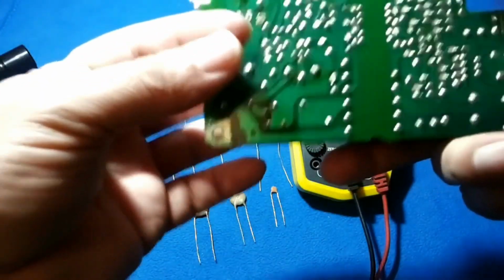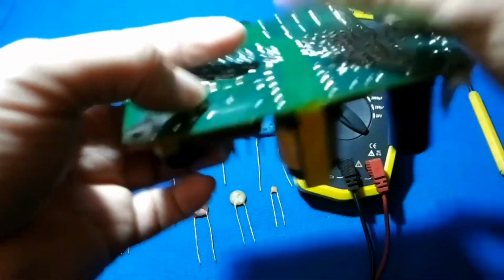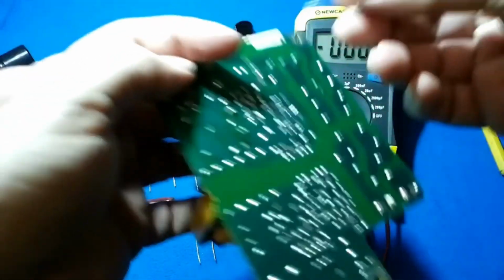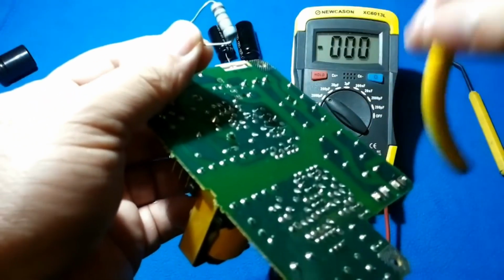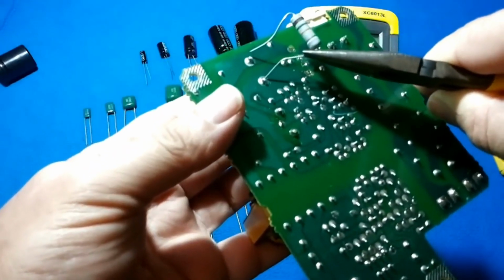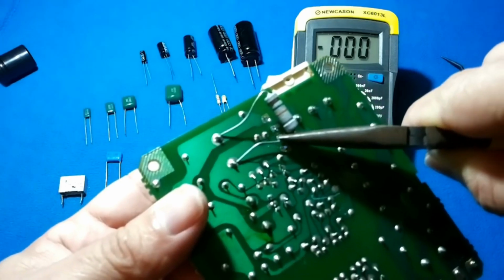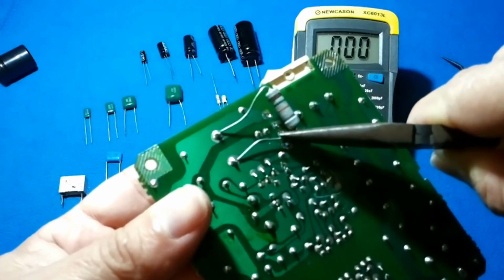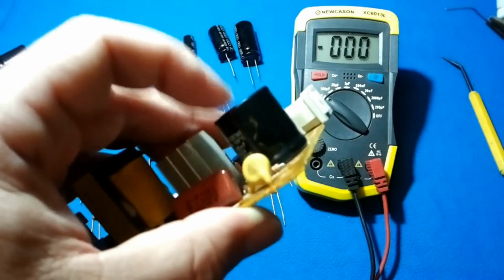Safely discharging capacitors is crucial before conducting any tests, particularly with high-voltage capacitors. Utilizing a resistor is a recommended approach for discharging them securely. The risks associated with high voltage require a cautious approach when handling capacitors. Exercising patience during the discharge process significantly reduces the chances of accidents while working with electronic components.